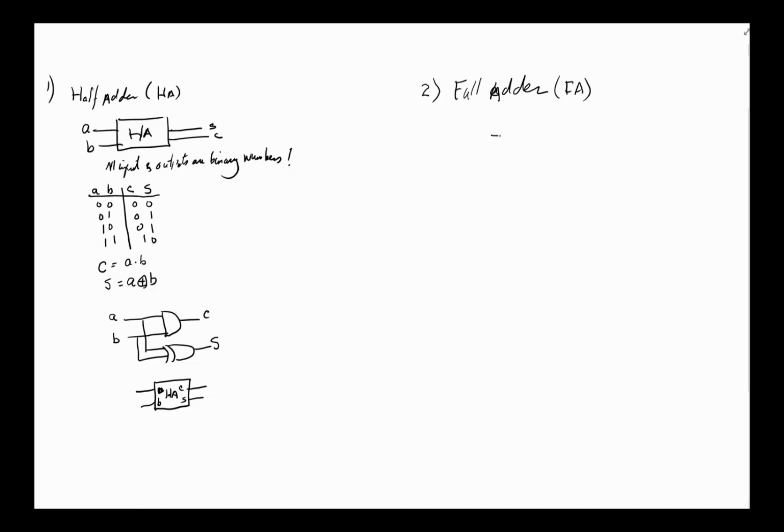The system diagram for a full adder would be a full adder, which eventually we're going to call a module. The full adder will have 3 inputs coming in: the 2 operands, A and B, and then a C in. What's going to come out is a sum, which is the sum of all 3 numbers, and any carryover, which we're going to call carry out. Hopefully the names will make sense when we get to the third stage and build a larger adder using this. So that's great.